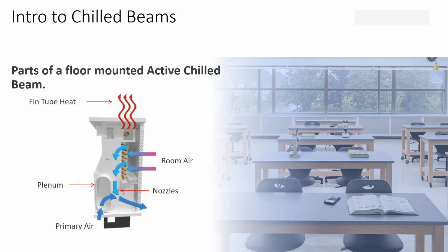In this case, you do not have the active nozzle portion around the fin tube area, so that's just going to kind of kick on, open the water valve as needed when in heating, and allow the space air to kind of pull through that perf face, heat up through that fin tube, and rise up to condition the glazing requirements.